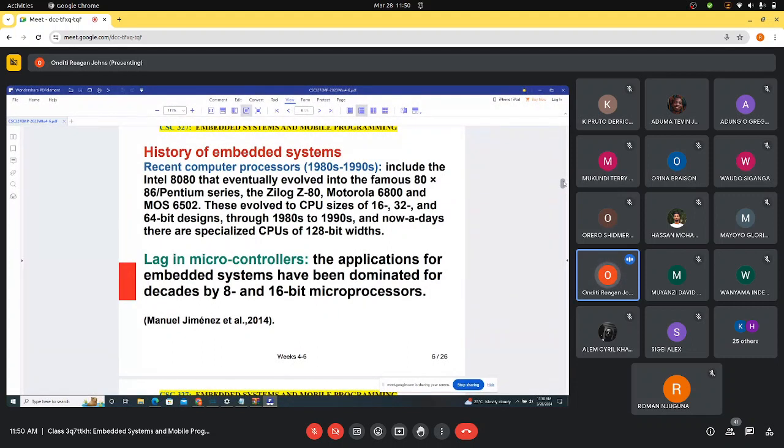These are the speeds at which the microprocessor would be able to operate within its logical zones, working with the clock speed, the logic speed, and the data speed. Actually there are 3: we have the data and the address speeds. So once you understand how the address, the logic and control, and the data bus work, you'll be able to understand what we mean by 16-bit, 32-bit, 64, and currently 128-bit width.